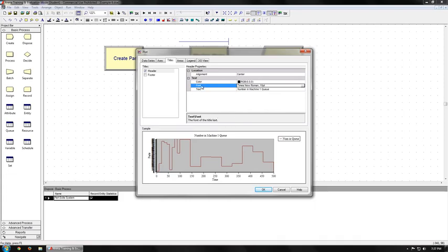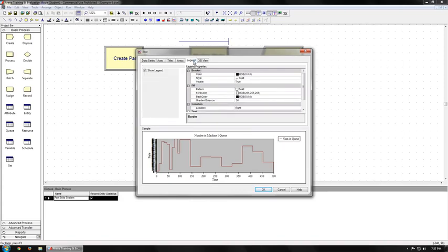Alright, and then if you click on another box or whatever, it will update down here. So here's a preview. And the last thing here that you'll notice is there is a legend, even though there's only one entry. So a legend doesn't really do us any good when there's only one entry, so go to the Legend tab and uncheck Show Legend. So that way we have more room to actually show the data that's pertinent to what we're interested in.